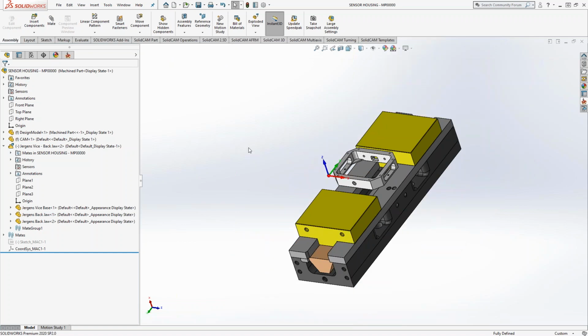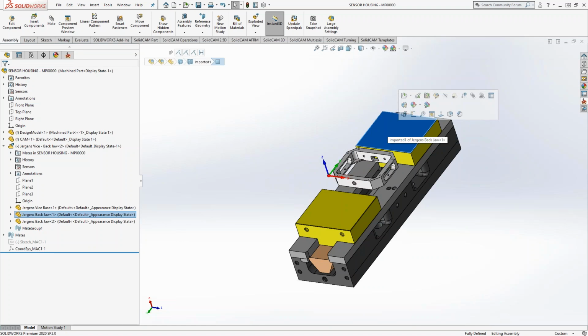And you can skip a lot of this if you want to just get going. The drawback of that, though, is if you do a misclick and you shift something, any definition relating to the locations of these solids will be disrupted. So your toolpaths will probably want to recalculate, or your fixture definitions will want to be recalculated. You'll break some sort of associativity when you shift the part.